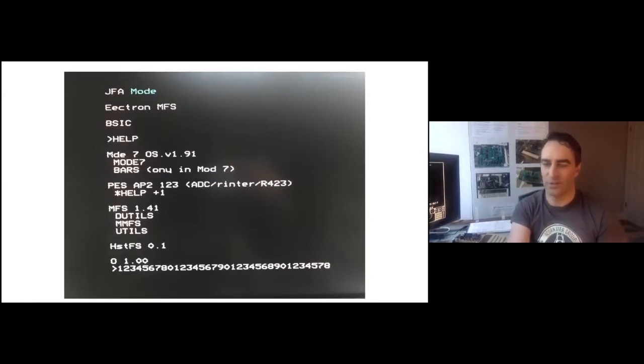So what I had to do, to get the mode 7 character data, was write code that would read it out of the QPI flash and write it into the SDRAM. So before the Electron boots, it does this little burst of reads from the flash and writes into the SDRAM. Sorry, not into the SDRAM, the block RAM. So yeah, and also I got the clock wrong. I forget exactly, but I like how this looks.